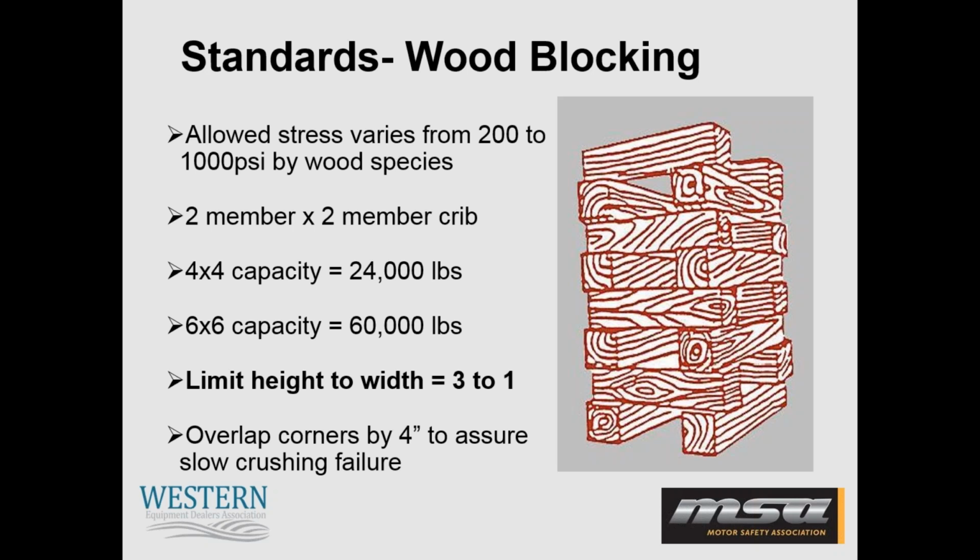But one thing to consider as well that I'll leave you with is limit the overall height of your crib to the 3-to-1 ratio. That's something I want you to retain after this webinar. So basically, if you have a 1-foot base of your crib, you don't want to build that crib higher than 3 feet. So keep that in mind. If we double that to a 2-foot base, we can have a 6-foot height in crib. So just keep that in mind and respect that 3-to-1 ratio.